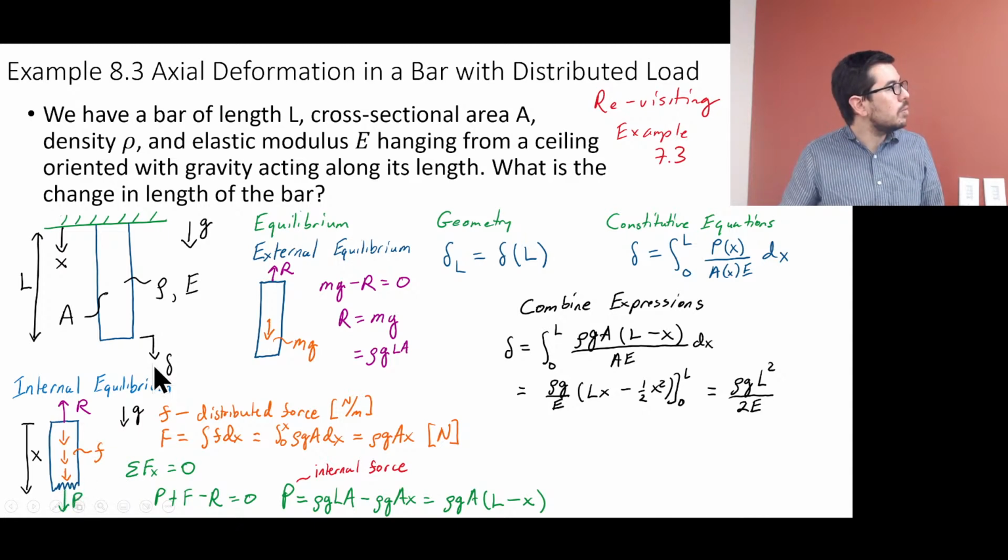If we want to figure out displacement at the end here, we probably want to use our constitutive equation, essentially the integral of P(x) over AE dx. So we want to use this, which means, once again, we need an internal force. Not the external one, but the internal one.